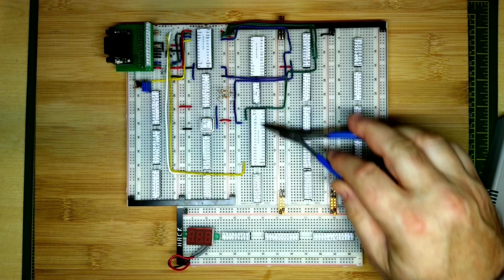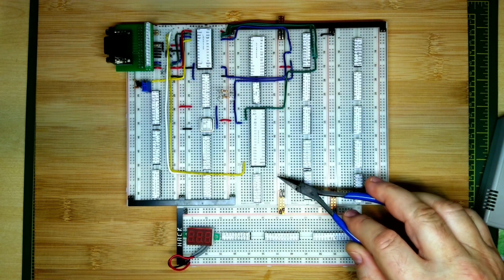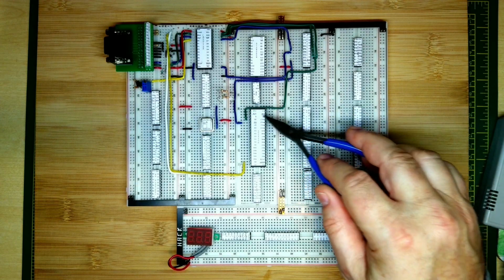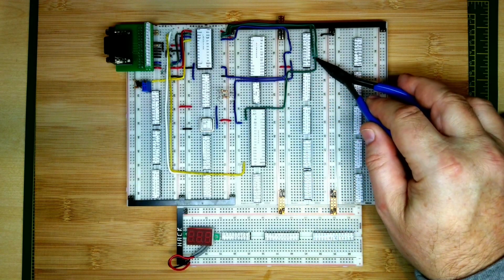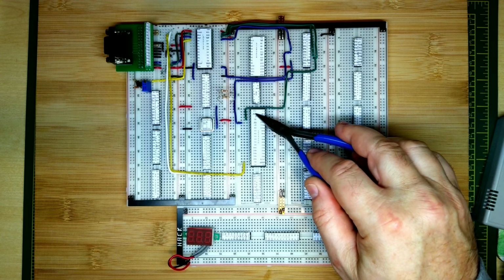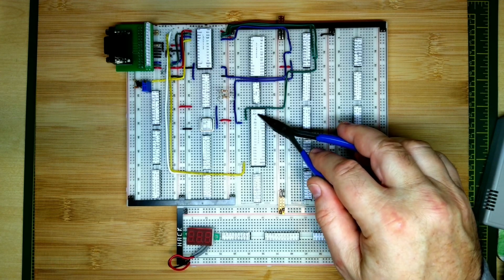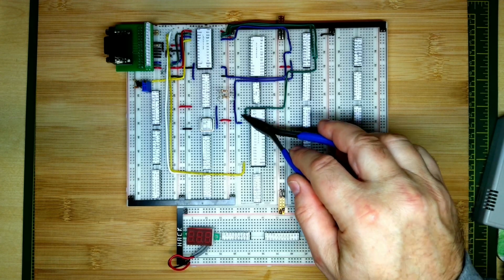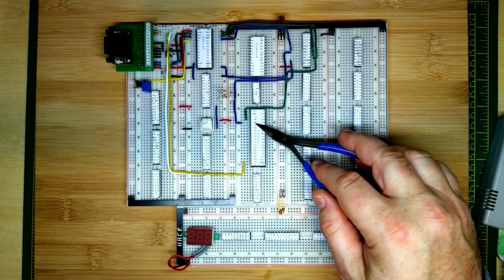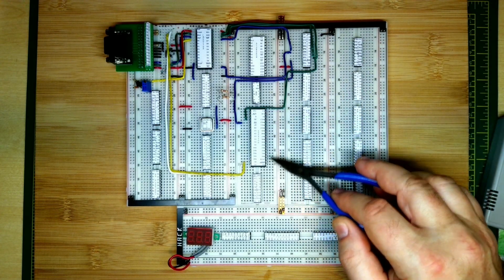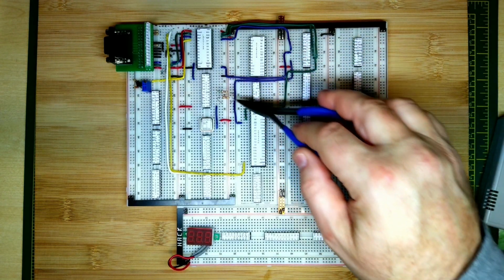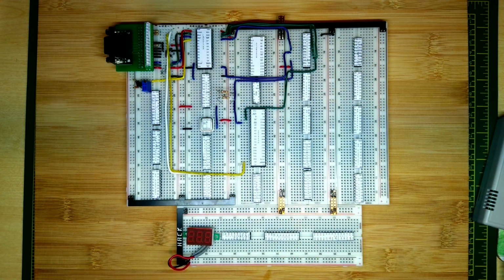So now we need to wire up the CRTC. We're going to need to do the power. There's the clock. The read write is probably going to need to go to the IO write signal over here. There is the E clock signal that comes from the main decoder on the main board, so we are going to have to worry about wiring that in at some point in time. We've already done the chip select, and we also need the display enable to come out of here and go into the blank input over here. So there's a few things there. Let's look at the schematic.